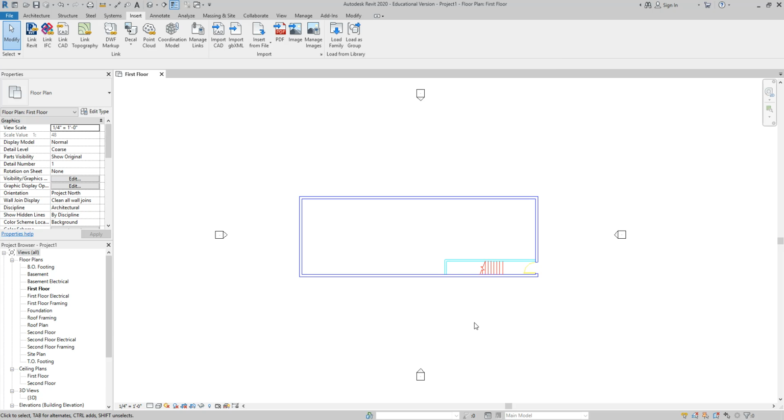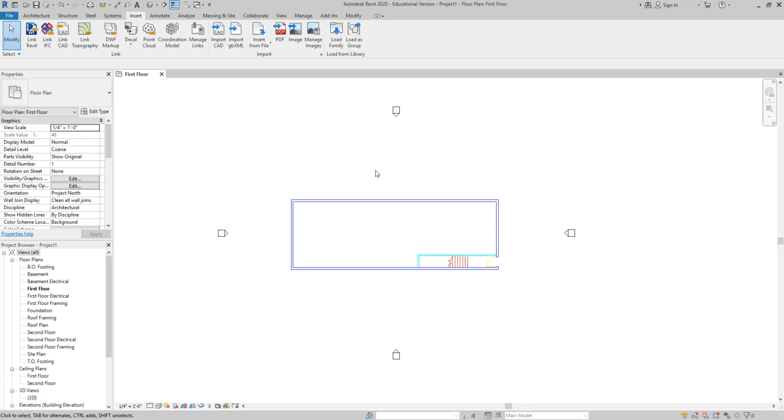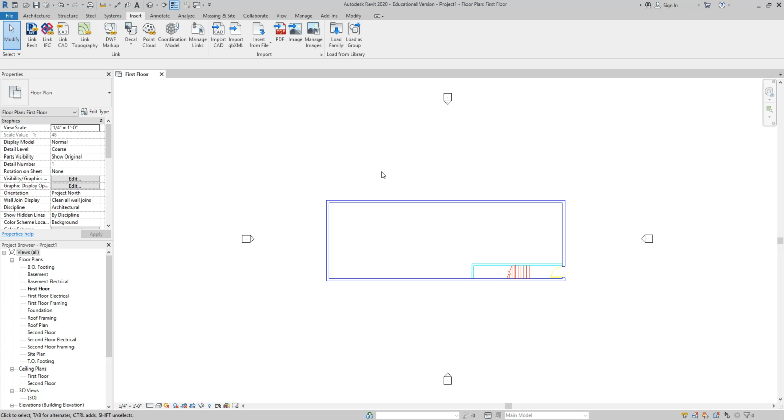Okay, and mine came in essentially right where I wanted it to go. It didn't go off to the side or far crazy or anything. Now, let's say it came in and I couldn't see it. What could I click on my mouse to try and find it? A double click zoom all, right? If you do a double click zoom all, it'll find it wherever it might be.